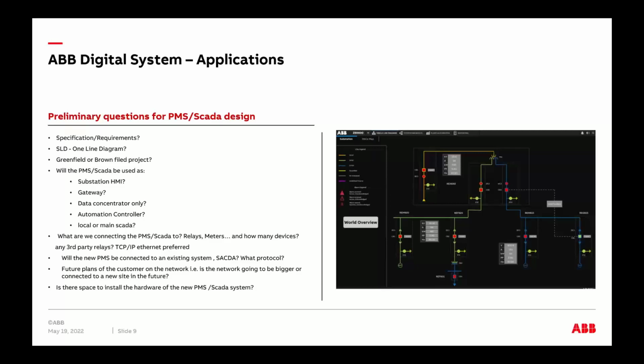You need to know also if the system is going to grow in the future. I'm starting with 10 devices, 15 devices, maybe in 1 year, 2 years, 3 years, that will be 300 devices. So you need to make sure you give them the right licensing from day one and also the right hardware. You don't want to lose face with the end user by telling them, hey, if you need that, then I need to charge you more licensing, and it's going to be more money for them. They will not appreciate that. You need to give them a heads up ahead of time.